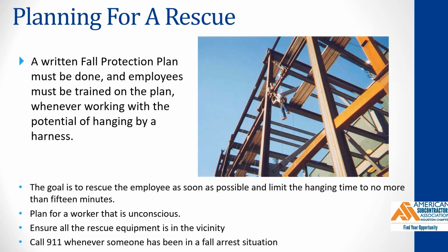Whenever working at heights where there is a potential of hanging from a harness after a fall, a written fall protection plan must be done and employees trained on the plan. The goal of rescue is to get the employee down as soon as possible and limit the hanging time to no more than 15 minutes.